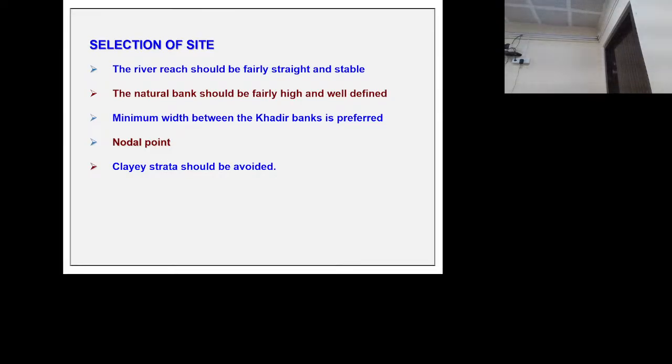If you have given 10 bays for water flow, only 5 bays will have actively flowing water, and in the other 5 bays there will be siltation on the upstream, so that they will be choked up. Afflux will be very high at this position and siltation is very high. If you are constructing a barrage, barrage is for diversion of water.